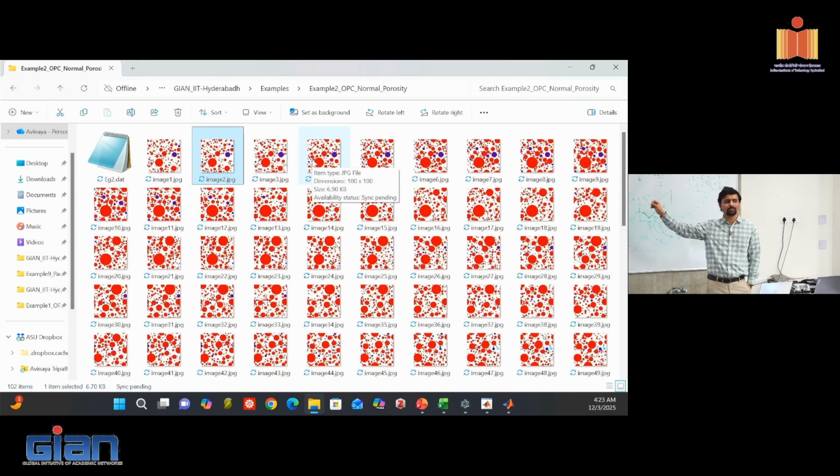Now there was no space to put some particles. Let's say if I added 1 micron particles, it has more space to put them, right? So I can keep on adding 1 micron particles till it jam packs. Let's say you already have this OPC. How do you want to pack it? Maybe start with a 4 micron particle. Maybe you can get a material that you can sieve such that it just has 4 micron particles. You start adding those into the system. That jam packs it. Now start adding 3 micron, 2 micron, 1 micron particles.